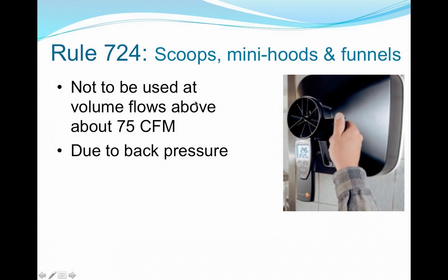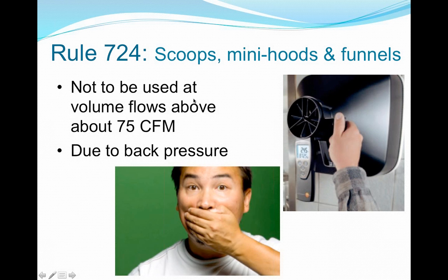But they can be used in low flow measurement situations. The thing to think of here is how much airflow can you get if your measurement device is actually covering the grill. You can still be pushing on it, but you're not going to get very much airflow in or out of that supply or return grill if you have a restriction placed over it.